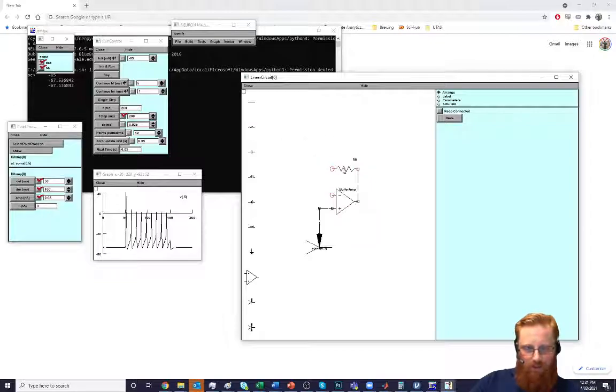And so let's put a feedback resistor and a resistor to ground. And we'll put ground there. And then we'll connect up our wire from there to there. And we have now made a two-fold amplifier, because basically the whole point of this op amp is it's trying to make this inverting terminal, this input here, the same as this, the voltage being equal.